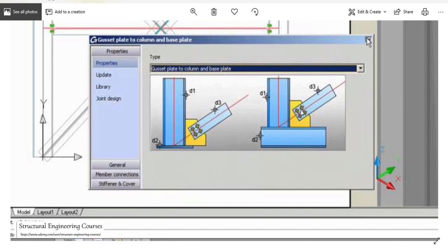So it may result in the underestimation of the axial force and bending moments. As I told you earlier also, we need to bridge the gap between physical models and analytical models. So what we need to do is make sure that in fabrication drawings, or on the site, the center line of the structural steel member shall be on the center line of this column only.